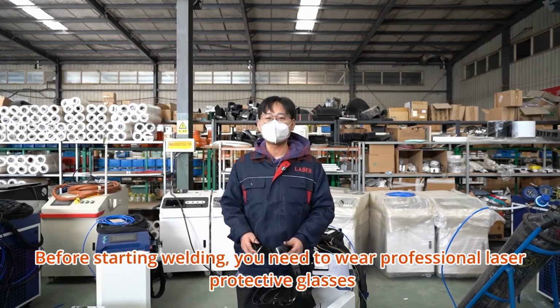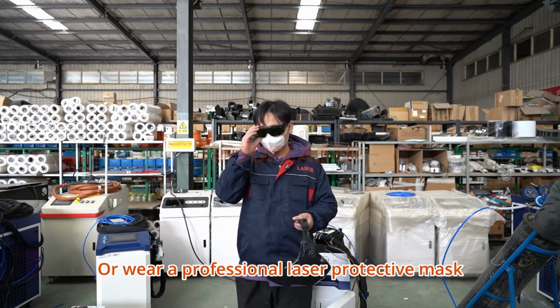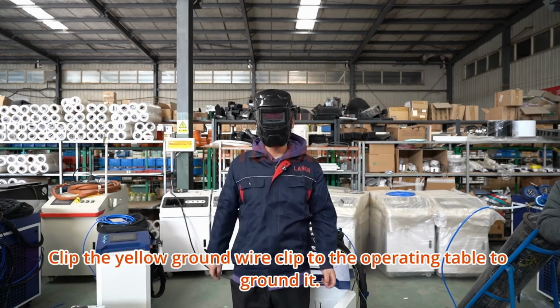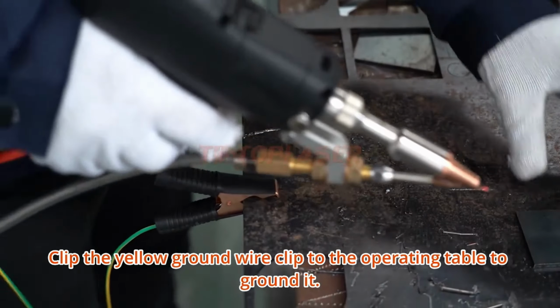Before starting welding, you need to wear professional laser protective glasses or wear a professional laser protective mask. Clip the yellow ground wire clip to the operating table to ground it.